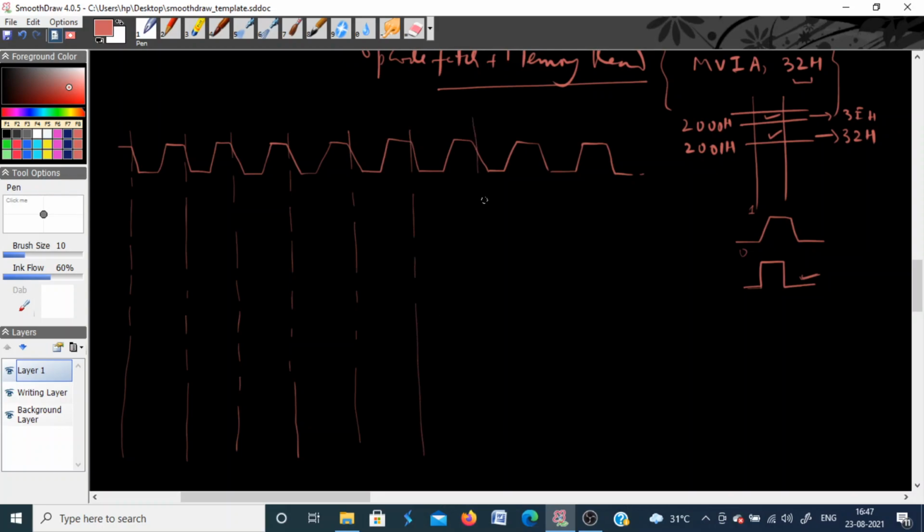So your different clock cycles, which we now call T states. This is T1, this is T2, T3, T4, T5, T6, T7, T8, of course, which is not used. So you have 4 clock signals, 4 clock periods. Now the first part is opcode fetch, and it requires 4 T states. This you already know, but I'm repeating it so that you get it revised.